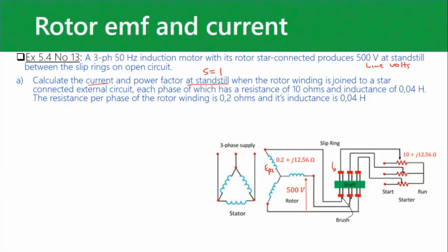What they've got now, that's why you have these slip rings, is external starter resistors. Just to limit these high startup currents. Now they've got this one. Usually it's just resistance. For some reason they put reactance in it, which kind of defeats the object. You only really want resistance. So this is the rotor impedance, and this is the starter impedance. It should be really puzzling to me why they would have reactance, but so be it.